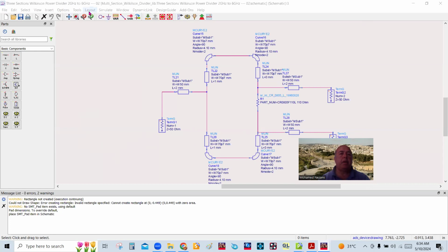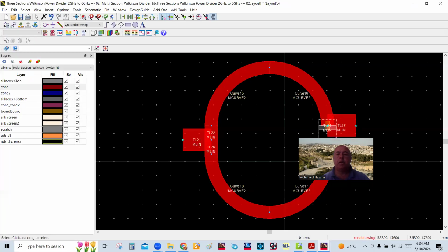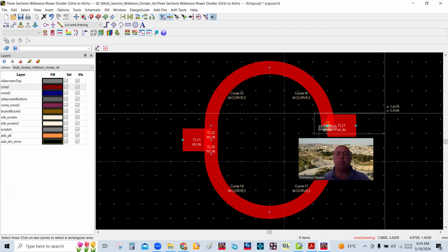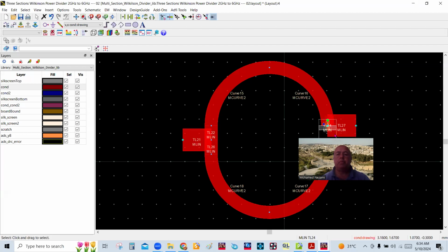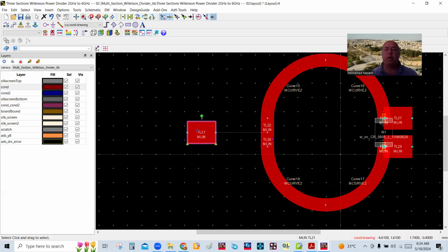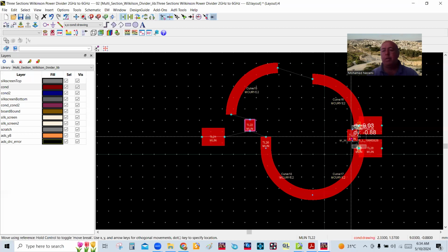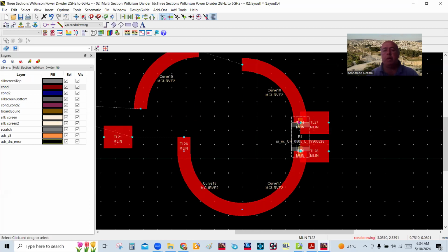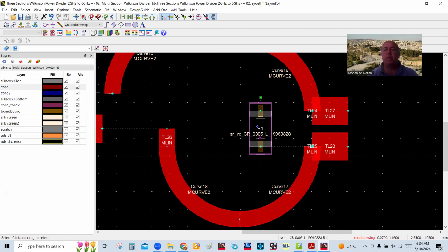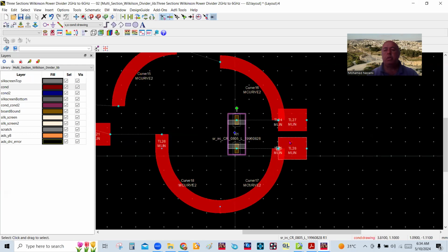And if you go to the layout of this, of course, this is the layout for this one here. Okay, so basically you end up with, this is the 50 ohm line, okay? You end up, this is an arc, and this is the line, okay? And this line in here really is what enables you to come in here to this package resistor in here. This is an 0805 resistor. And then, of course, you have the output case in this case.